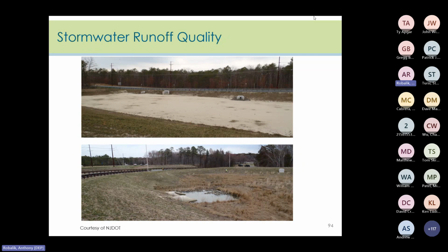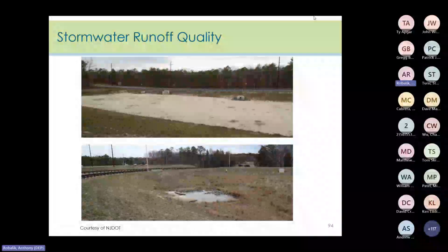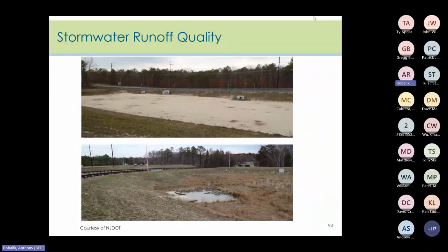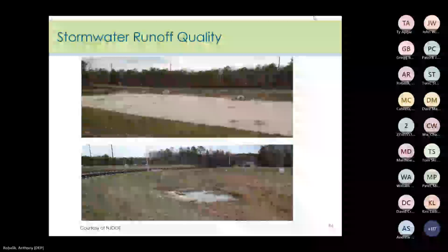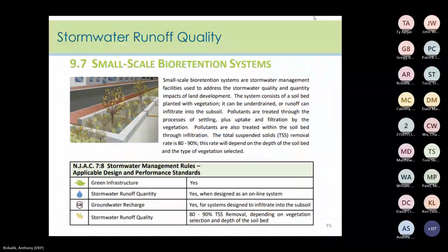Additionally, the vegetation that is breaking down in standing water forms a biofilm that can cover the sand layer and greatly reduce the basin's ability to infiltrate. And that's why the BMP manual does not allow for a vegetative bottom for an infiltration basin.